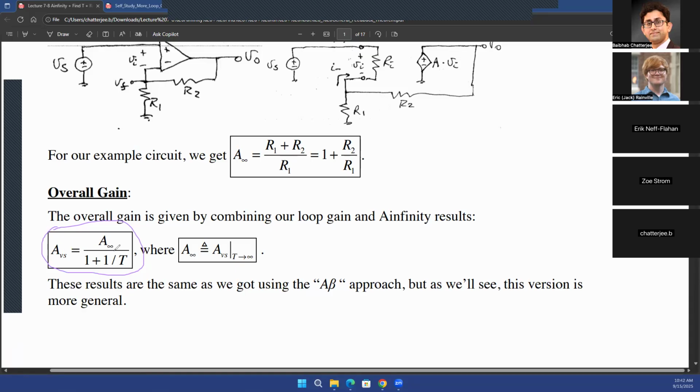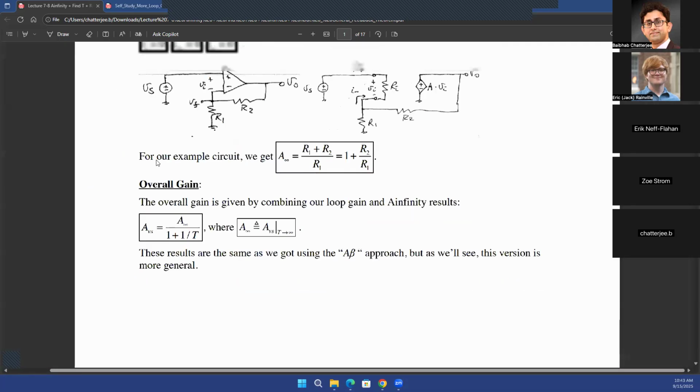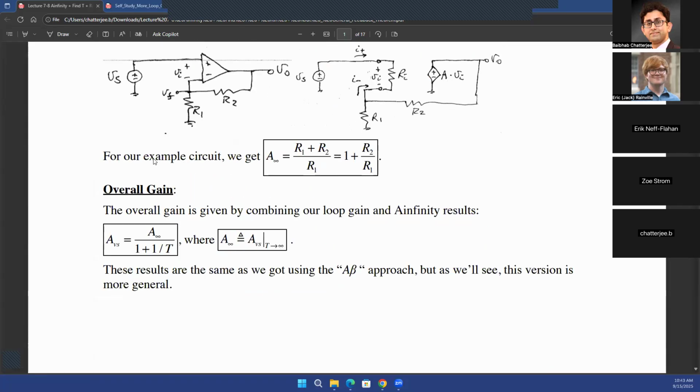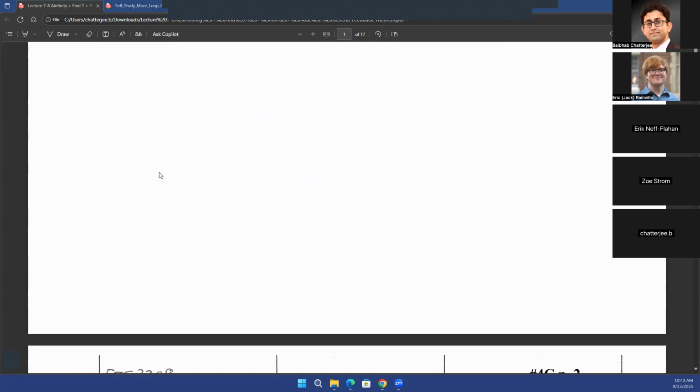The denominator has your loop gain, which is T, and T is equal to A times beta, where beta is your feedback factor. And all the non-idealities related to your finite input impedance and non-zero output impedance are factored inside beta. Okay. So remember that this is going to be the most important equation for both your homework 2 and homework 3. And of course, in future, whenever you're dealing with any non-ideal op-amp, that's the equation that you're going to use in any kind of analysis.